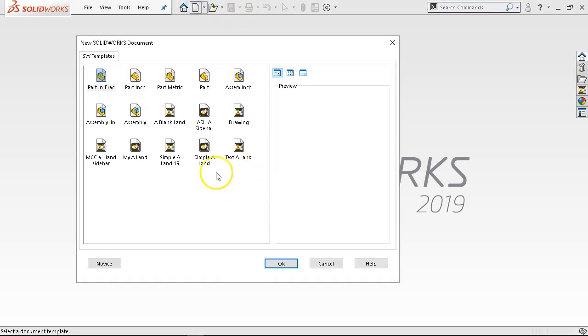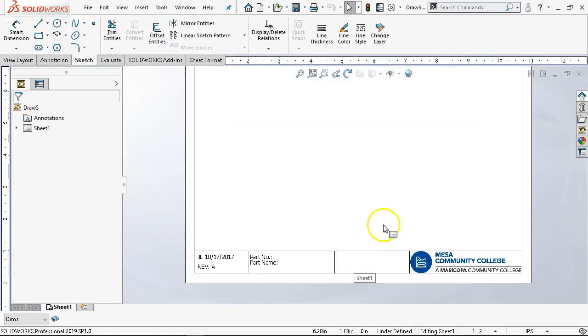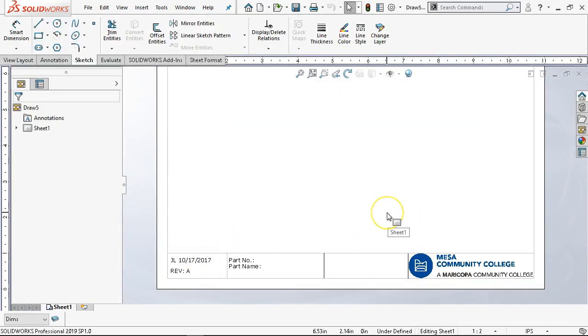All right, one more to look at is going even further. All right, so I like the format. Way back when I started board drafting, we had the 3/4 or an inch across the bottom. And so this one didn't really fully develop. I would probably go back and reduce the size of my logo, make sure to put in the tolerances, and the thing that we were missing was the icon that told us if it was first angle or third angle on the last one. Would put in the icon, and that's something that we could make into a block and be able to manipulate as a group.